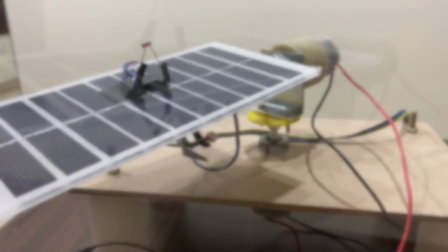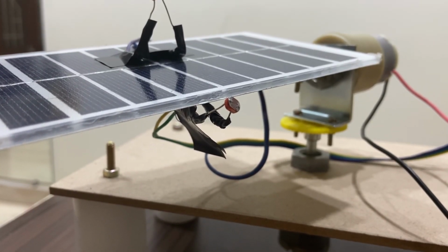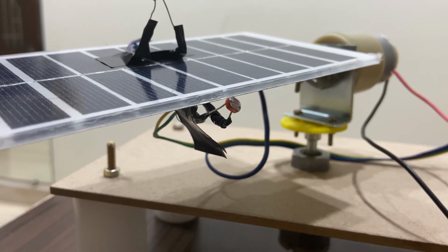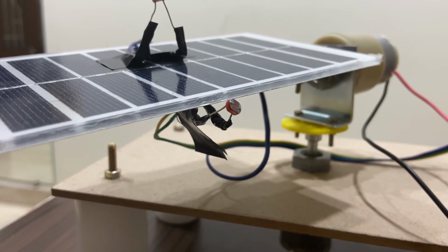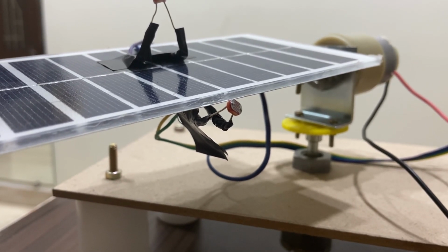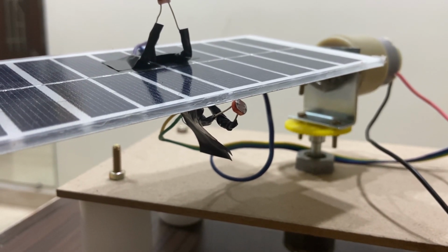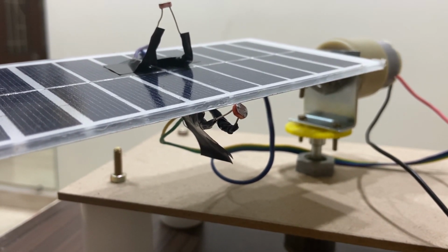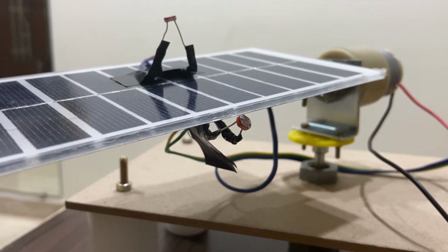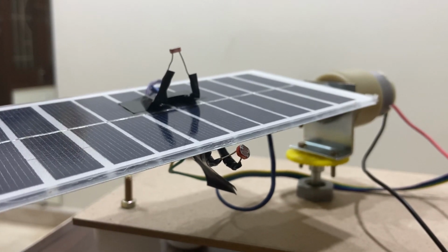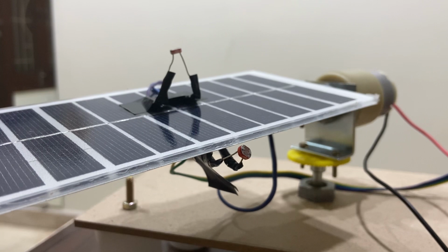on any sensor. For the third and the final case, let's consider a greater intensity of light is incident on the second sensor here. In this case, the base motor should rotate in anti-clockwise direction until maximum intensity of light is incident on the second sensor. And then the top motor must rotate in anti-clockwise direction until this maximum intensity of light is incident on sensor number 1. All these cases are taken into consideration while programming the Arduino board, and the final program is uploaded